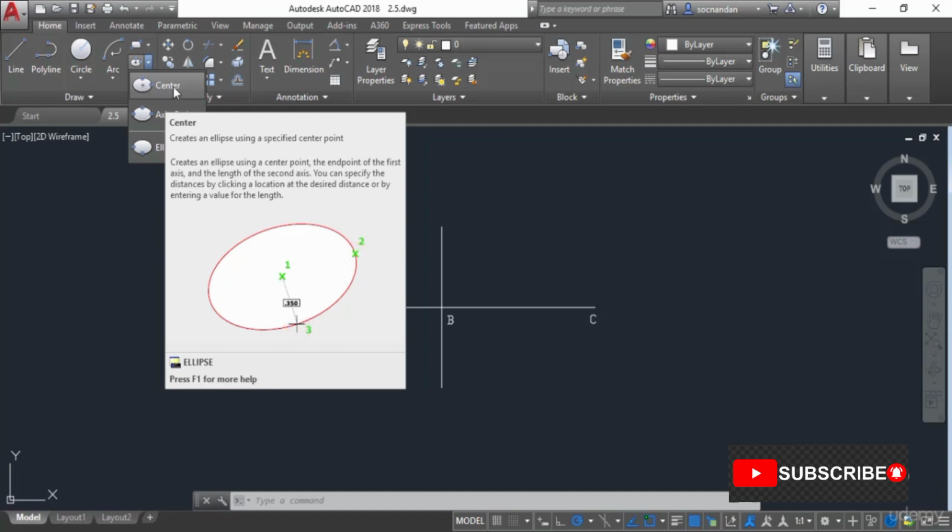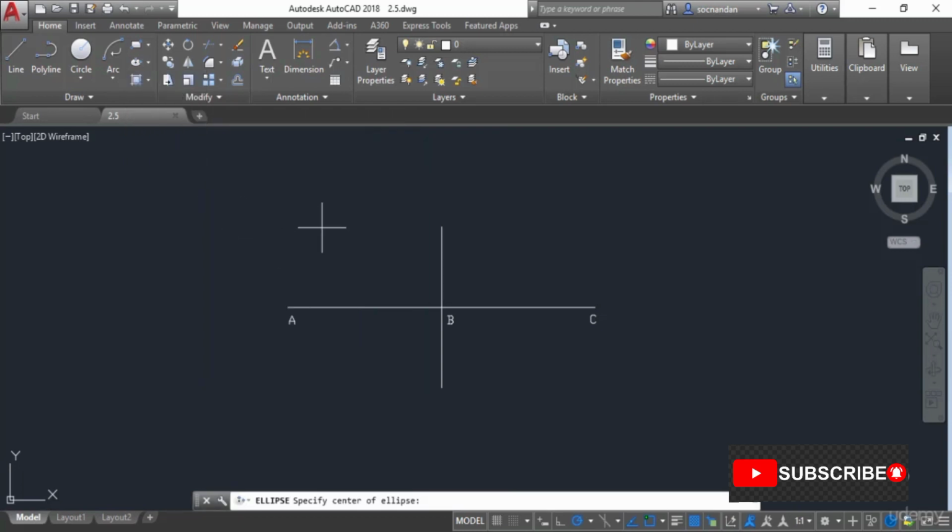So we'll do this on this geometry. So I'll select this center end ellipse. Now obviously we need to specify the center point as mentioned on the command line. So we need to specify the center of the ellipse. So that center point will be point B in this geometry.